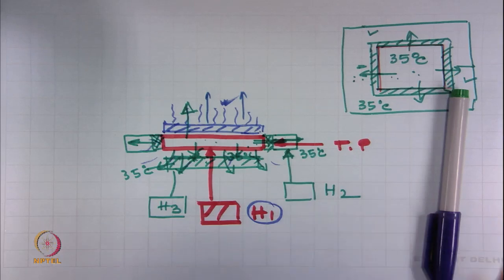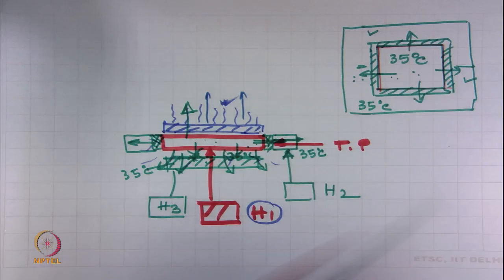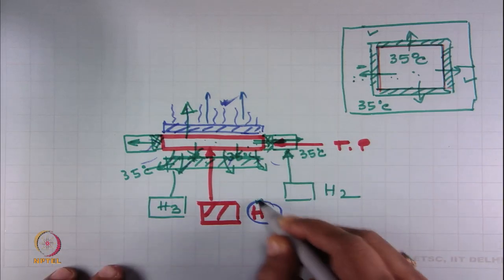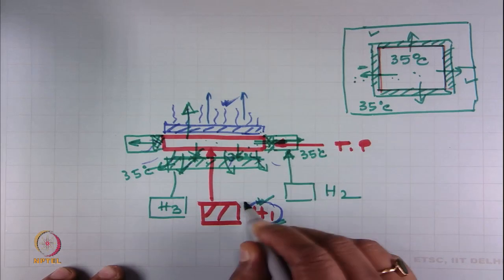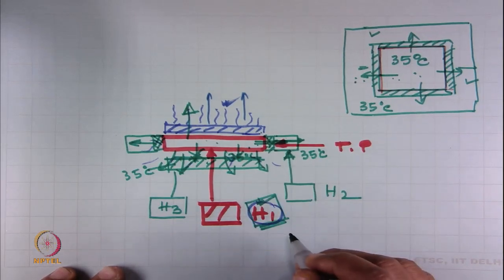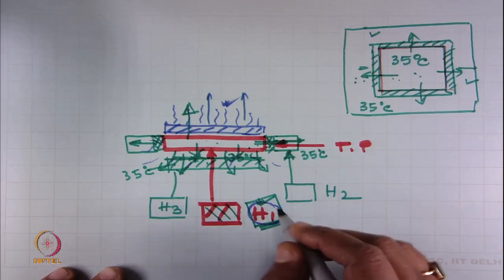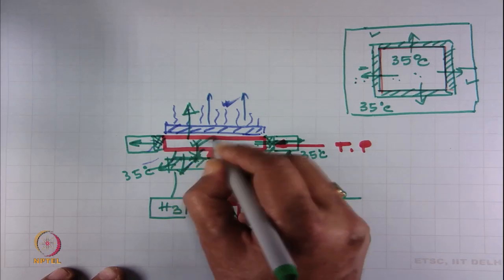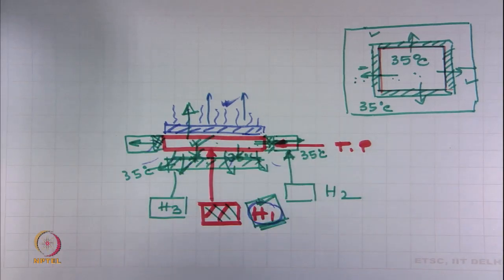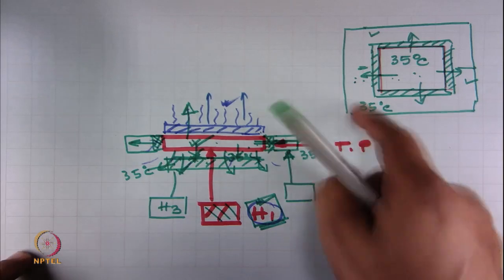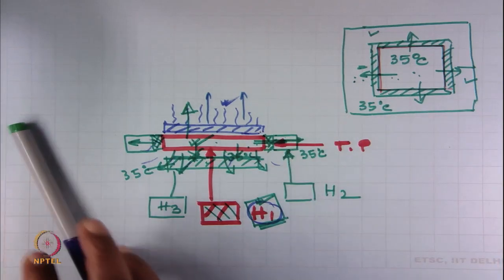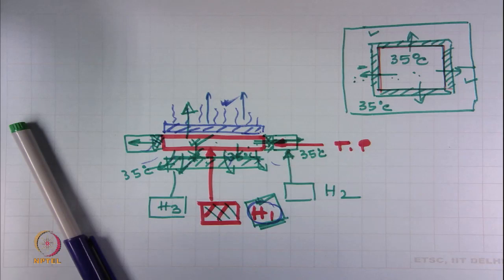and that is how we can directly measure the heat which is flowing through the fabric, and this heat is provided by heater H1. That means, in the guarded hot plate we measure the heat which is provided by H1, which is heating only the test plate, and the heat for the bottom plate and guard ring we normally do not take into account, these heats are required to maintain the same temperature.